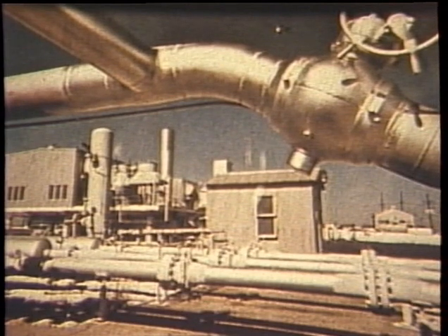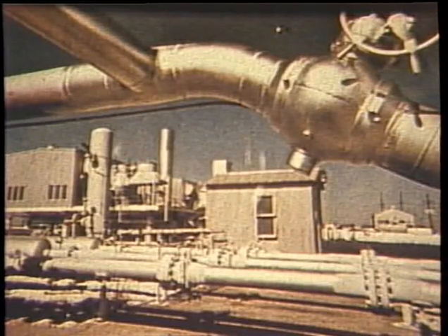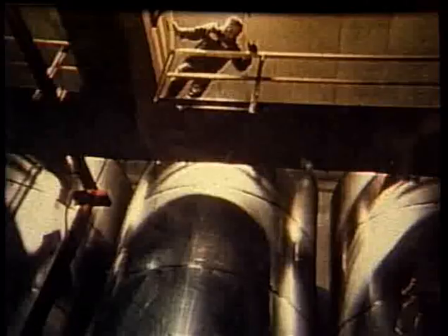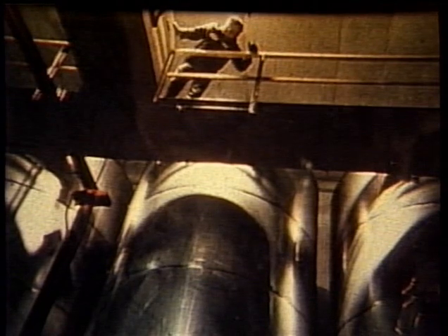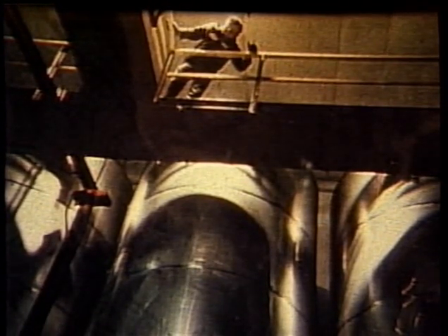Selection is also based largely on the degree of quality required for the weldment. Visual or magnetic particle testing may be all that is needed for verifying weld quality on low-pressure piping. However, radiographic testing would likely be required for critical high-pressure applications.